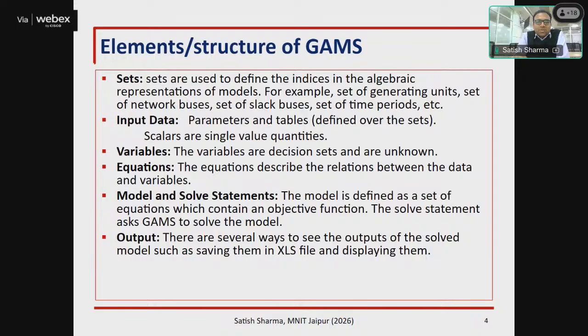Then equations, just like the equations which we have defined in our MATLAB. In MATLAB we defined that some constraints are equality and some are inequality. We have to provide all the equality constraints together and all the inequality constraints together, linear ones separately, and if non-linear ones are there, then in fmincon they will be provided with C and Ceq, Aeq, Beq, and A and B. With the same logic in fmincon, we can provide three kinds of equations: equality, linear and non-linear, and inequality, linear and non-linear.